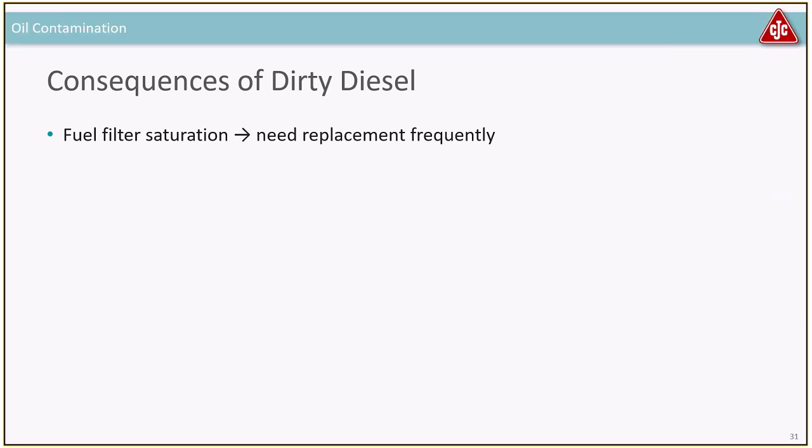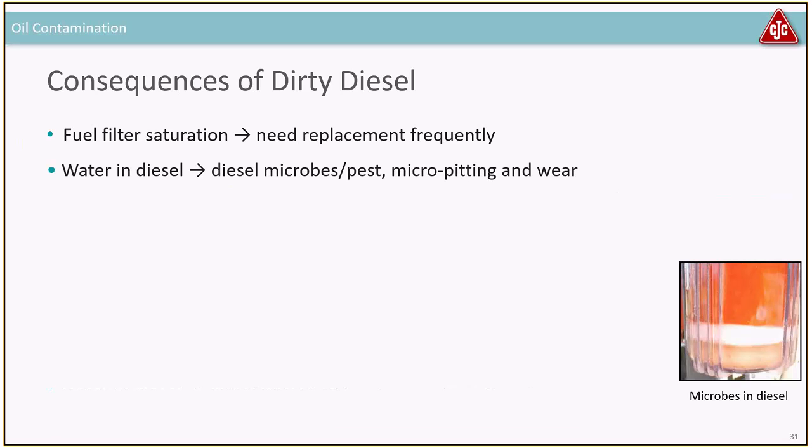Fuel will also have problems with your filter. You need to replace your filter. You can also have water in the fuel that will create microbes, or diesel pests it's called, and of course pitting and wear on your injectors and pumps. This is a diesel pest you have here. So this is the diesel pest feeding on the diesel, and then when the microbes die, they become like slimy stuff here in the bottom, and you don't want that in your engine or in your filters.